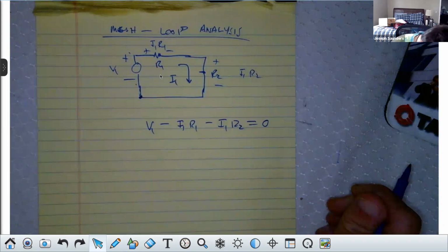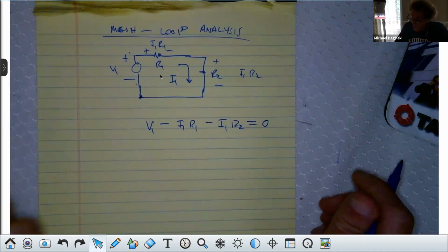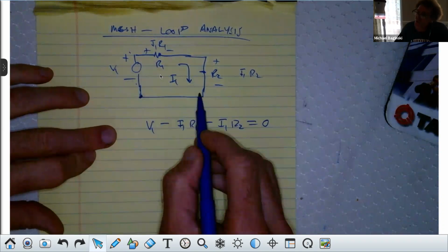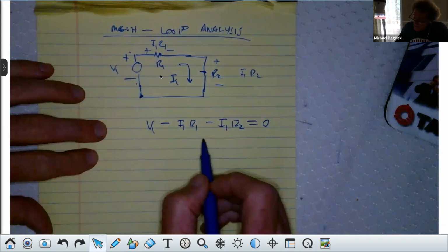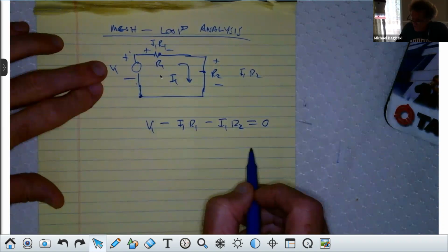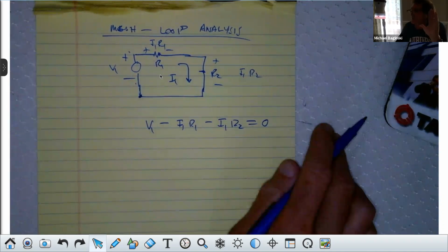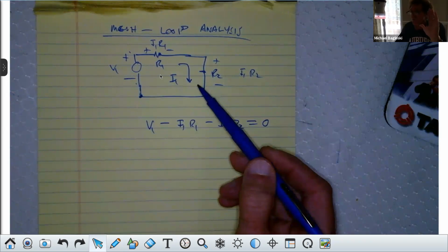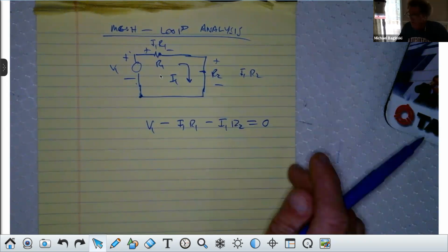Okay, good. Now, I did this. It's extremely simple, and this is called a mesh current. You'll notice how it was localized here. There's nothing else in the circuit, so there can only be one current. And at this point, if V1 is given, and R1 and R2, you can solve for I1. And I'm not going to dwell on this. How many agree you could solve for I1 simply? And by the way, if at this point you can't see you can solve for I1 simply, you may consider dropping this course, because at this point, we're well beyond that. Everybody? Okay.